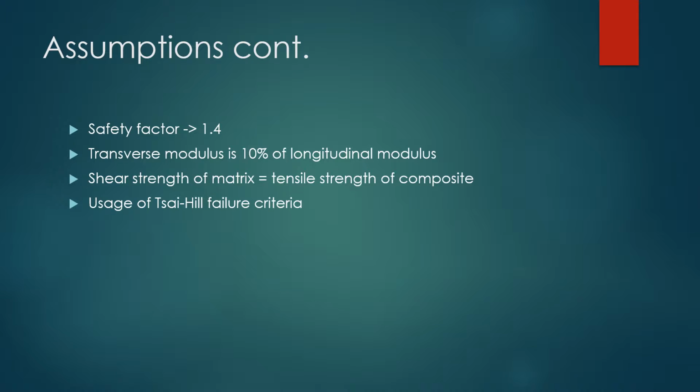This is based on two concepts. We took an average to determine material properties as a conservative approach, and shear for metals is commonly estimated as 1/2 tensile strength. Since the shear strength is dominated by the weaker material, it was decided to use the larger value as it better matched values for shear strength in commonly found composite lamina.